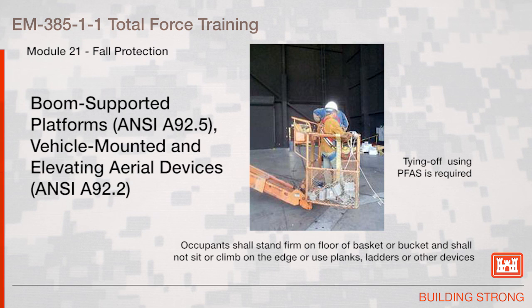Occupants shall stand firm on the floor of the basket or bucket and shall not sit or climb on the edge or use planks, ladders, or other devices. Tying off using personal fall arrest systems is required.